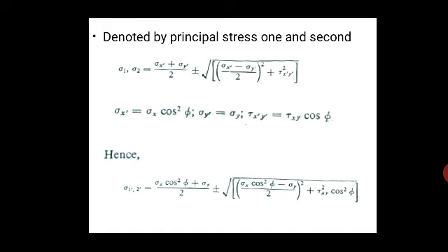And also from the sketch, for incidence along the y-axis, the appropriate stress component is sigma x only, since sigma z and tau xz are 0 for a plane stress case, which indicates that for an incidence along the x-axis, the appropriate stress component is sigma y. These are called the secondary rectangular stress components.